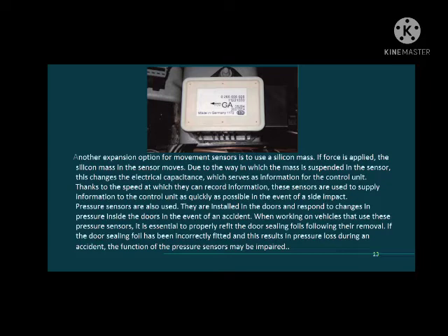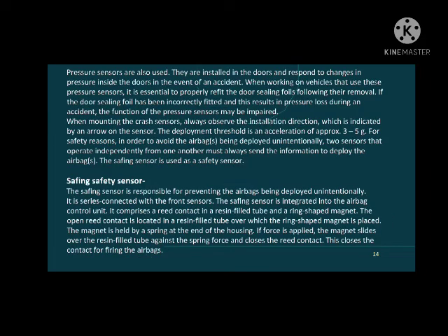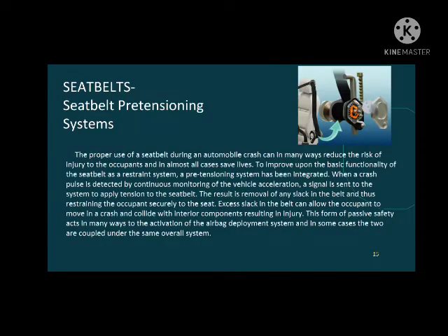After the airbag has been inflated fully, some gas is slowly removed to reduce the surface pressure, to absorb the shock that the driver and passenger receive. In case the ECUs are not supplied with power by the battery due to disconnection resulting from the collision, the ECUs are given a backup from the capacitor.